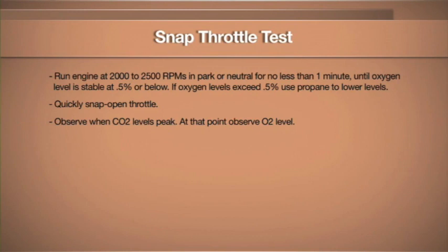The CO emissions are going to climb from the amount of fuel being delivered into the catalytic converter. At that point, all the oxygen is going to be used up trying to convert CO into CO2. We need to watch these levels to make sure the catalytic converter is capable of converting those CO levels into that CO2.